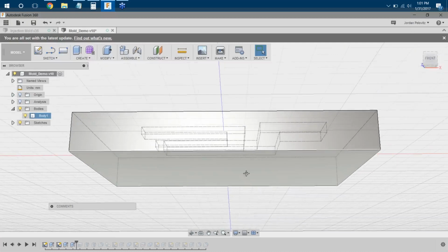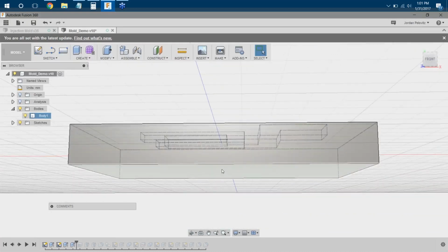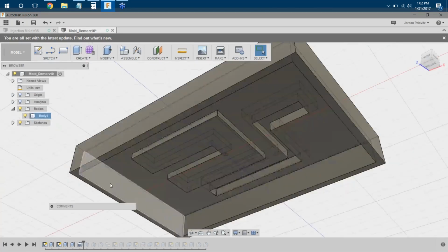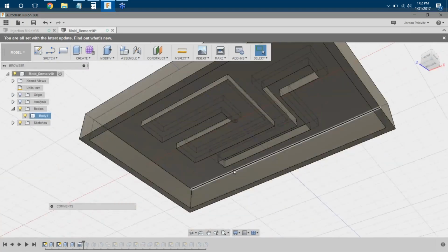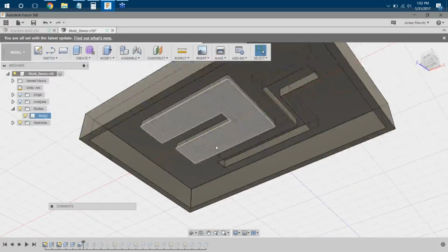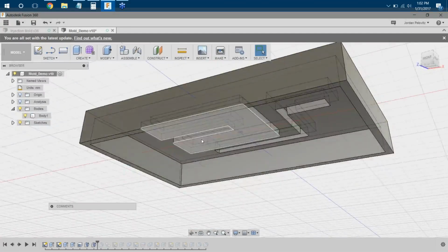As the outer plastic cools, it'll cool faster than the inner plastic. So the inner plastic is going to start to cool and pull that now cooled outer plastic inwards. So you get this kind of big divot on the inside. So you want to make sure your parts have a relatively thin wall thickness. You want to avoid big, huge chunks of plastic if you can. So the next thing I did was I added draft.